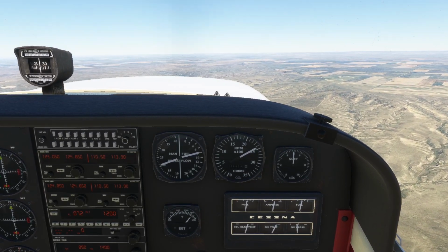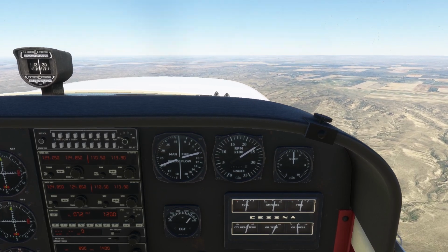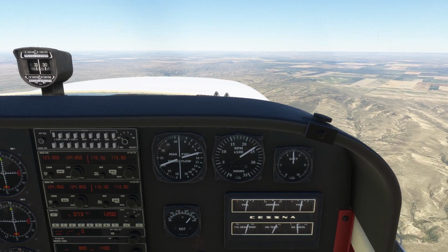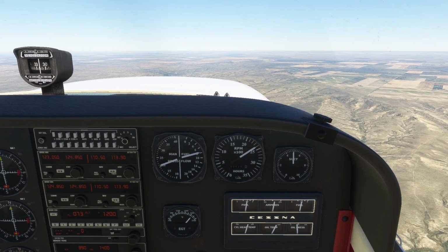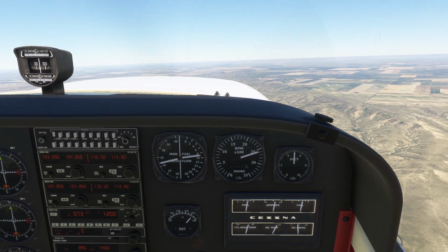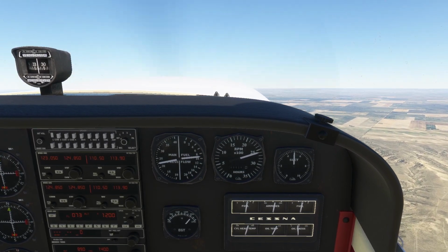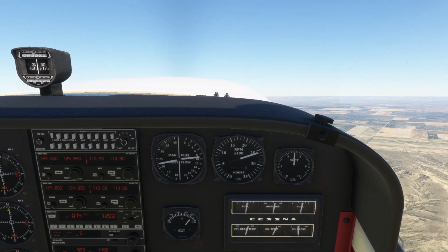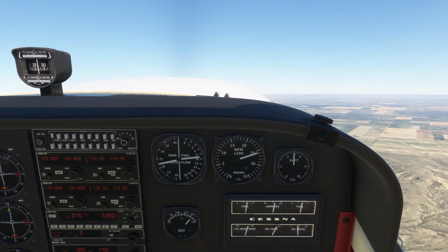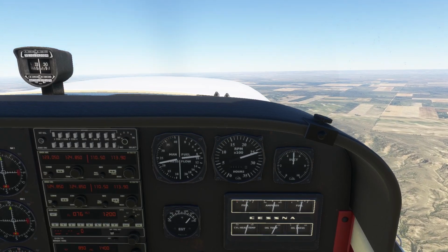Obviously, your RPMs are going to be in the thousands, for example, 2,500 RPM, as opposed to 25 inches of manifold pressure. For the sake of this argument, ignore the zeros after your RPM. We will call 2,500 RPM and 25 inches manifold pressure the same. The reason it is a general rule of thumb to keep the RPMs higher than your manifold pressure is so that you avoid excessive engine wear and damage.